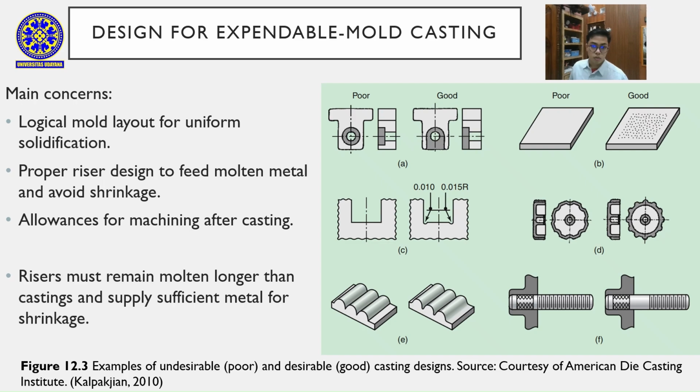In expendable mold processes, such as sand or investment casting, the goal is to achieve uniform solidification. Risers play a key role. They must stay molten longer than the casting to feed metal and avoid shrinkage cavities. The mold layout and riser placement are crucial for quality.